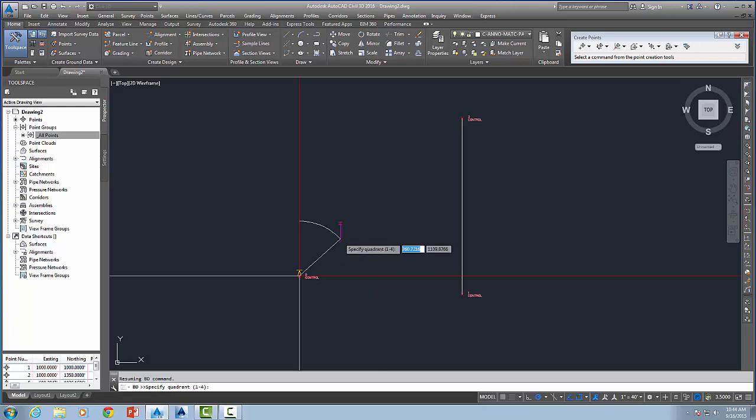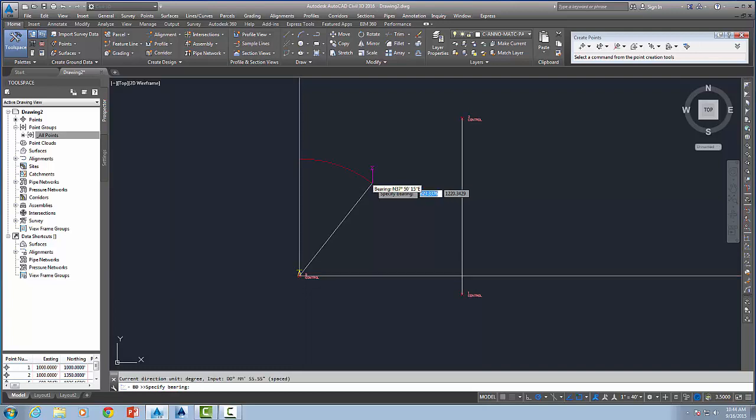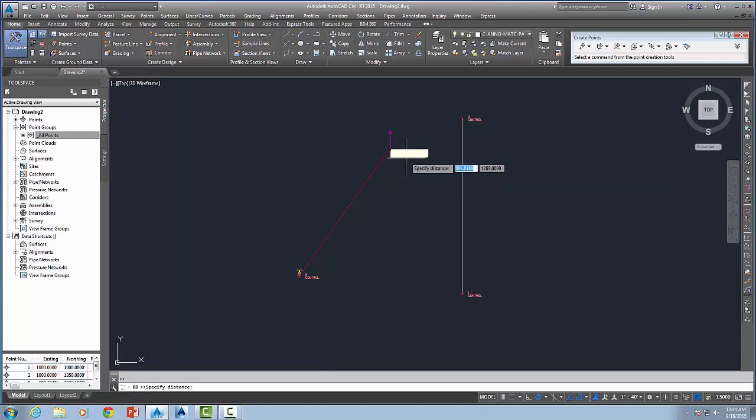So I'm just going to grab my point object O-snap, select it, hit the escape key, and notice what I'm doing now is in a bearing mode. So my quadrant, remember from last week, first quadrant is 1. Bearing is going to be 35 degrees. Don't worry about minutes and seconds if they're zeros. And the distance is, like I said, immaterial. I'm just going to drag this guy up about 300 feet and left click it and then hit escape twice. And so what I'm doing is showing it the distance. I could also type in a distance, but in either case it's really just as easy.